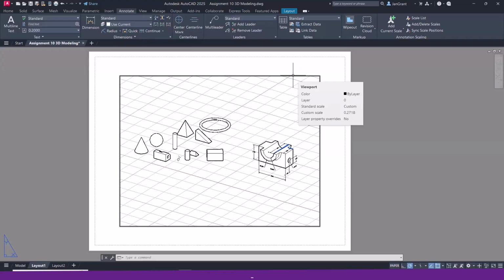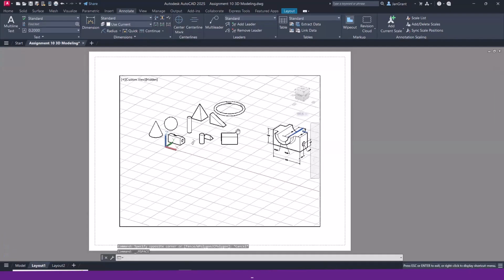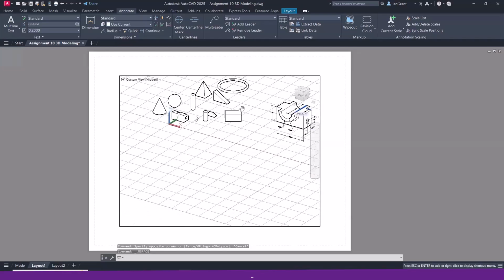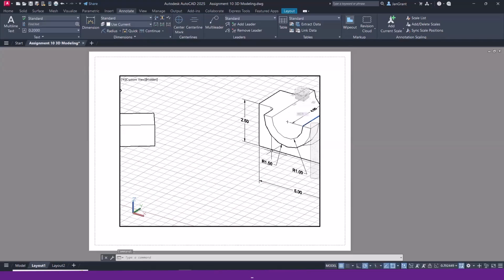It's kind of a layering system because you have the model space kind of below the paper space. So now you see how the origin, the UCS icon, is now a triangle at the bottom left corner, and it does say paper over there at the bottom right. Now, if you double click inside this box, you see how it puts you inside the hole? So you're in the paper, but you're accessing the project that you're working on.